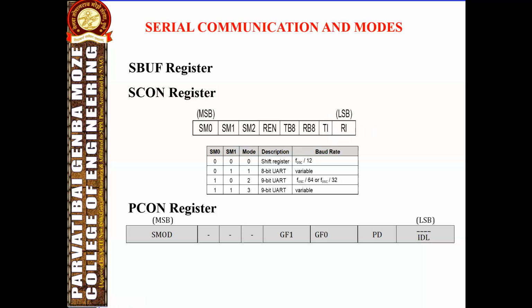These flags are used together to produce an interrupt to the programmer, indicating that the byte is received or transmitted, and hence to get ready for the next byte. The program must read these flags to find out which bit has created the interrupt and clear the bit.